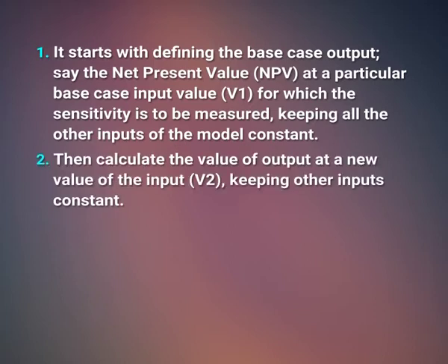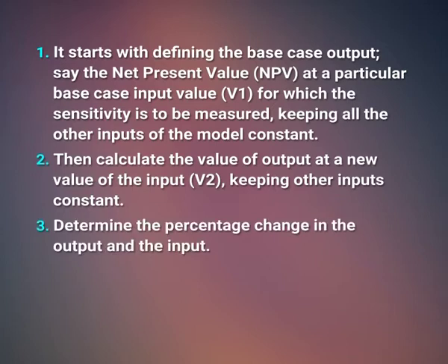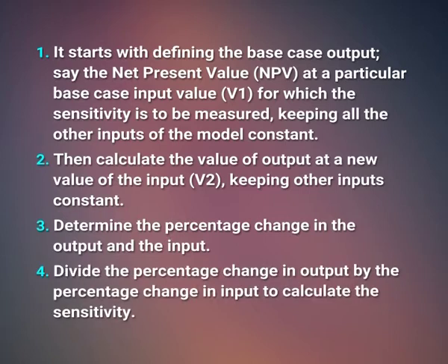Number 2, then calculate the value of output at a new value of the input V2, keeping other inputs constant. Number 3, determine the percentage change in the output and the input. Number 4, divide the percentage change in output by the percentage change in input to calculate the sensitivity.